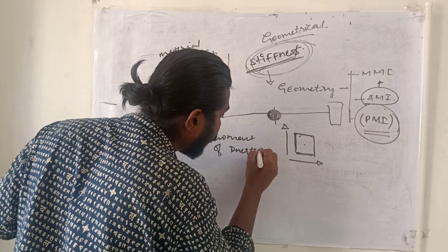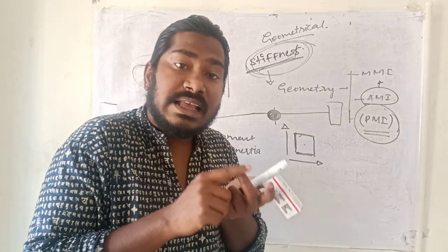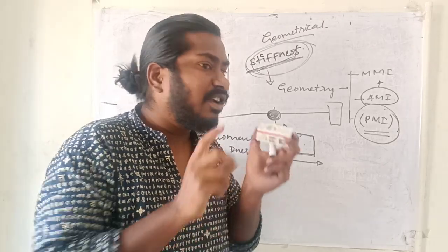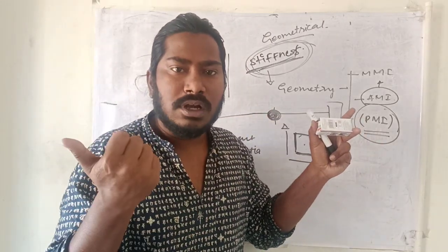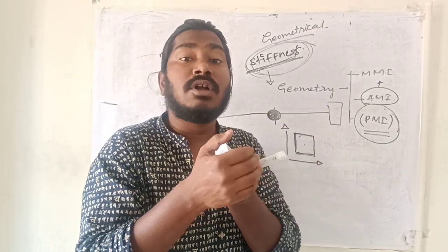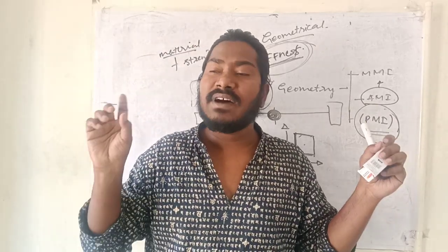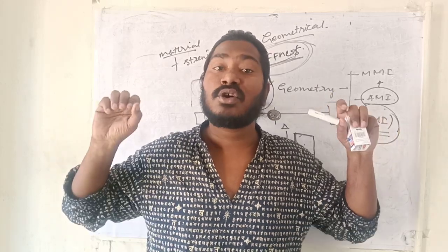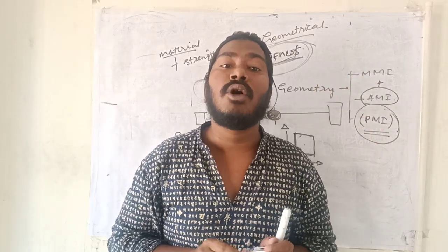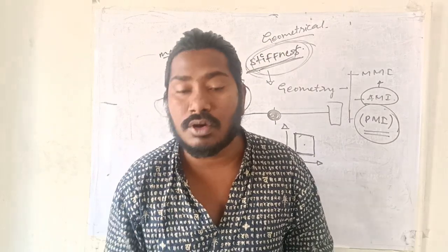We all know, if I take two bars having the same weight and same length, so their cross sections will change. If I have two tubes, a hollow tube and a solid bar, having the same weight and same length, it means the cross section of both the bars will change. The hollow bar is always going to have a higher value of polar moment of inertia in comparison to the solid bar. How?